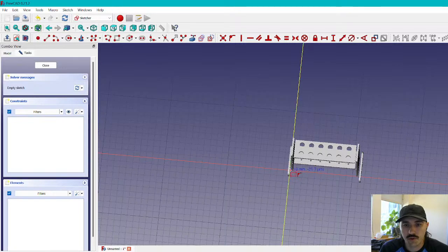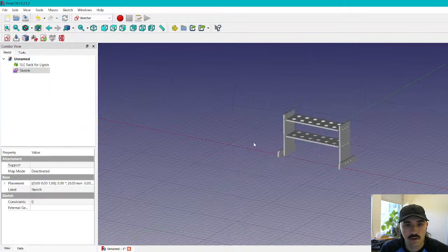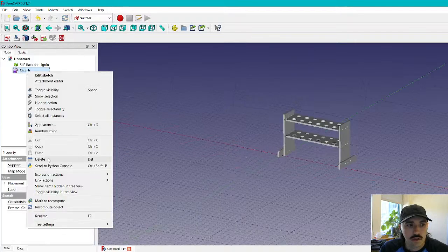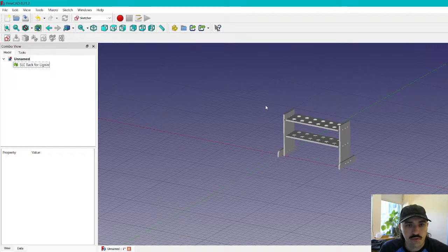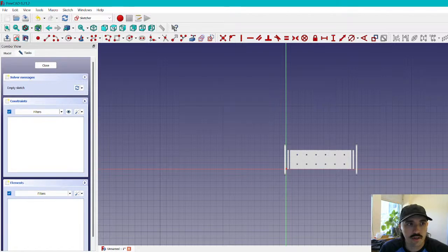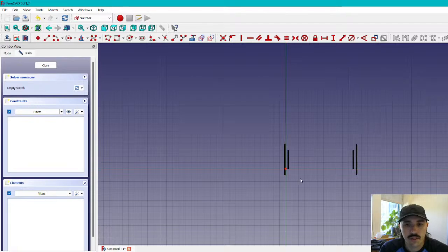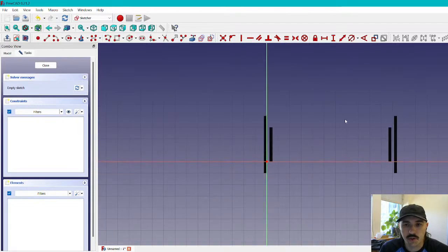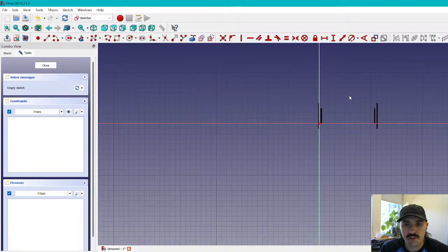Hold down Control, click, when we have the origin selected. Very tricky to use. Okay, try one more time. New XY plane. If we hit this View Selection button, it will just show us the plane that we're on, so it'd be easier to select everything.